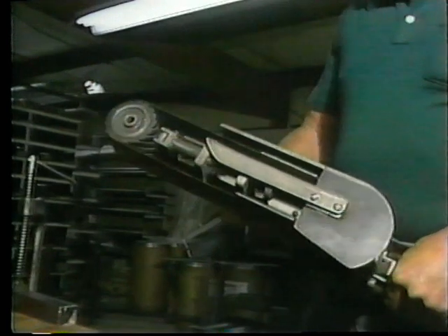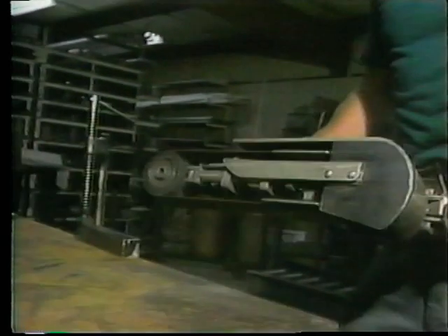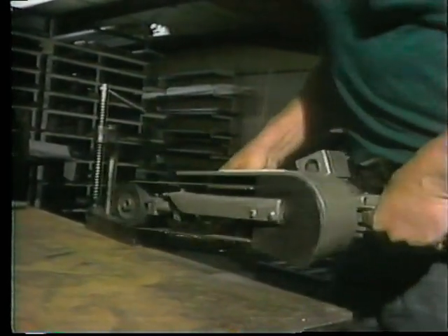Hear that? Know what it is? You're right. It's a piping air leak. And although leaks in pneumatic lines do not present a housekeeping problem like a leak in a hydraulic line would, they do waste air, reduce system pressure, and often reduce air tool performance. For instance, in certain cases, a pressure loss of just 10 psi can result in a drop in tool efficiency of 15%. That's why it's important to be on the lookout for air leaks.